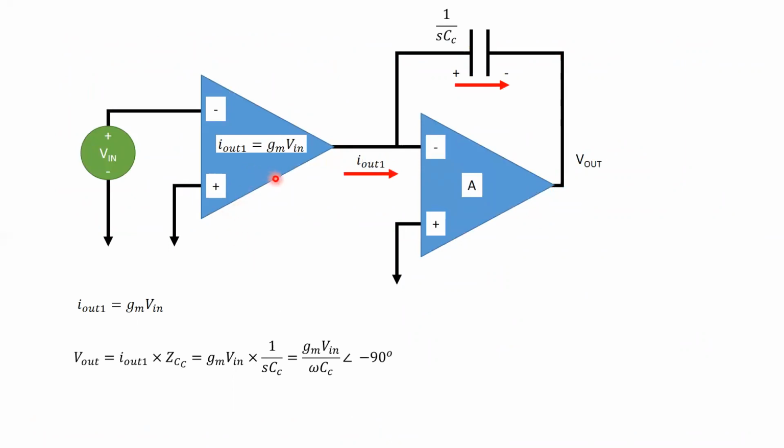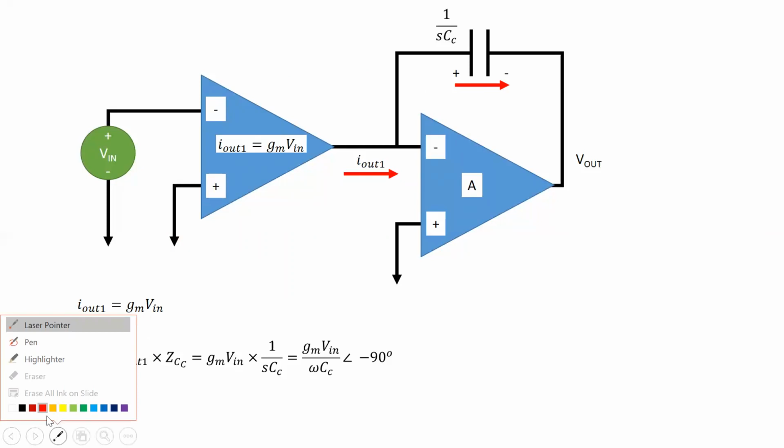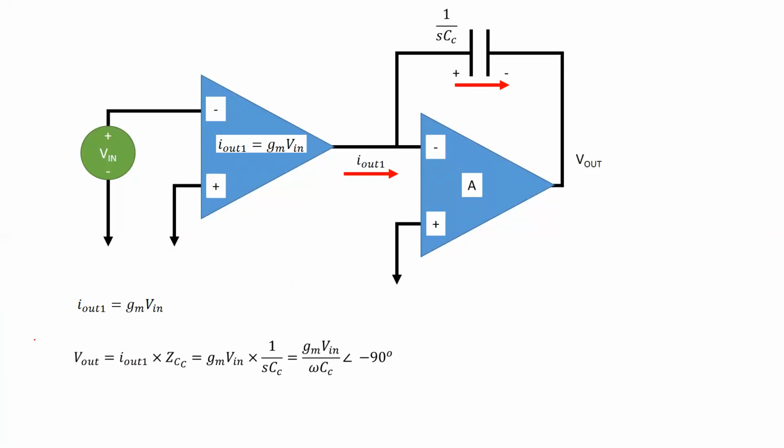So really, an op-amp has two stages. It has this differential mode stage, and it gives a current, and it's just GM times VN, right? Then it goes into a pure gain stage, which has this feedback capacitor. If we didn't have this feedback capacitor, you maybe don't understand the words I'm using yet, but what'll happen is you'll have an unstable circuit. So in fact, you probably can follow the conversation, let's say, a little bit.